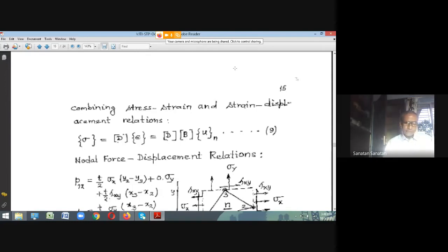So here again you get the stresses in terms of the corner node displacements. That's the beauty of these steps: once you have approximated the required surface in terms of plane tiles, the problem of determining the displacement surface is nothing but determining the displacements of the corner nodes under the approximation of linear variation of displacement within the element.